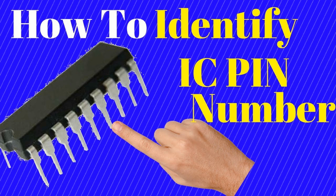Multiplexers, MUX. Function. Multiplexers are used to combine multiple input signals into a single output. They are commonly used to select one of several input lines and route it to the output based on control inputs. Input selection. MUXs have multiple data inputs, usually 2^n inputs, and a set of select lines that determine which input is routed to the output. The number of select lines determines the number of input lines that can be accommodated.